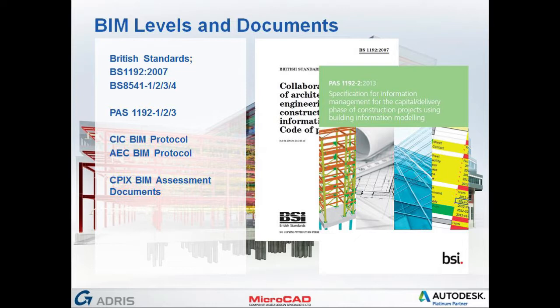We've also got things like the BIM protocols, so how you're managing things inside an office, and how you're going to manage things when it comes to the contract documents. The CIC BIM protocol is a link to your contract documents. The AEC BIM protocol is more about how you're deploying something inside an office.